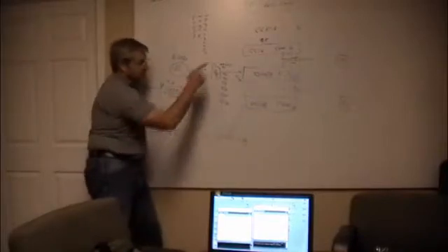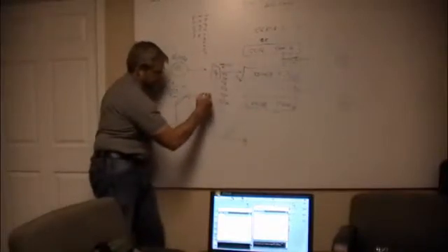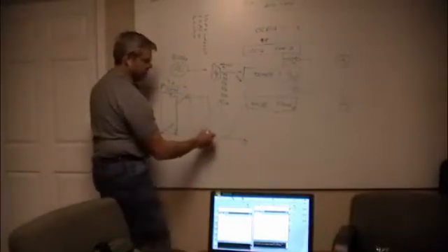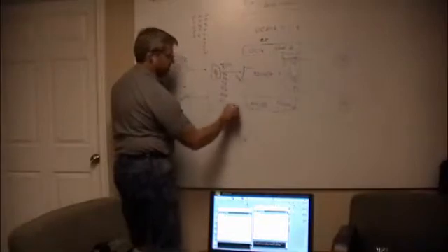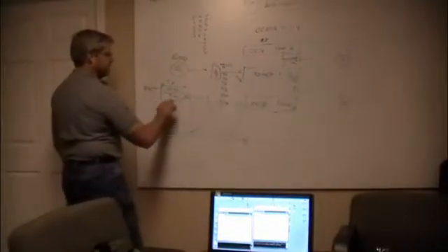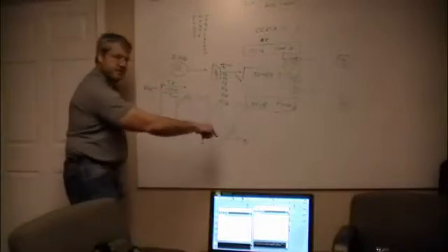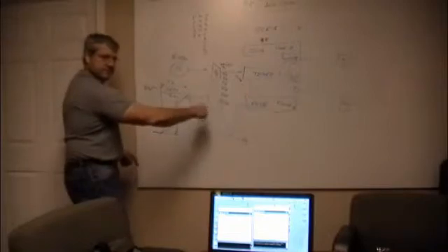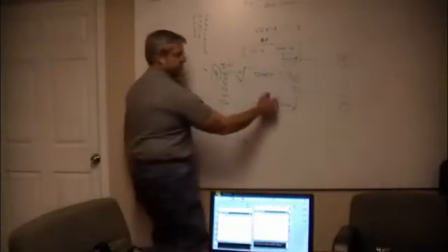It will come up. And then the next time that happens, it will toggle down. So toggle just means change the value. So now I've got a square wave that's going on at 32K divided by 8 million, right? It's half. The period is half. It's 2 full cycles.